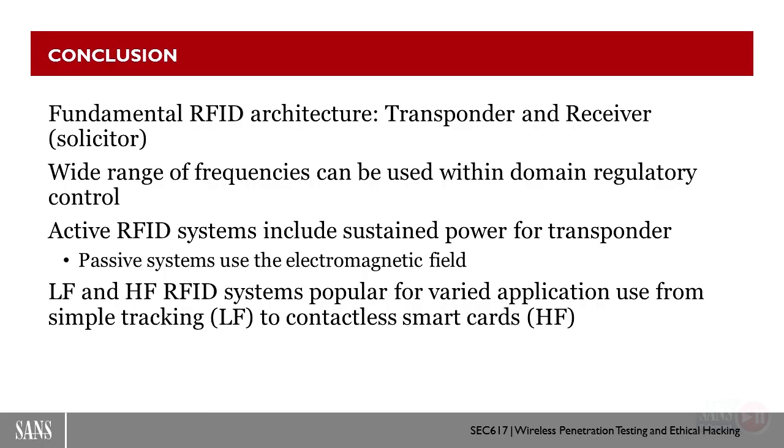The active RFID tag itself, the transponder, does require constant power. And maybe we even have the opportunity for a hybrid approach, in that we don't start transmitting with the battery power until we receive some RF energy to power up some other circuit. And we see lots and lots of adoption of both low frequency and high frequency. Low frequency, the most simple of those, is used for lots of asset tracking and inventory, and potentially even still some authentication, as well as high frequency with contactless smart cards, and then NFC as well.